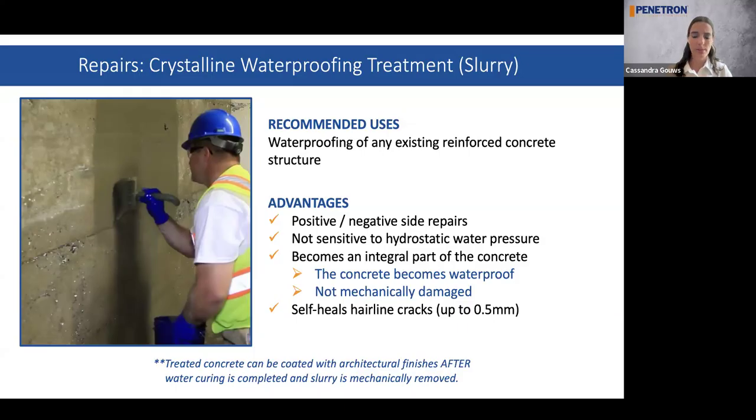And what I mean by that is if you've got, let's say, a basement, right, a concrete basement, your walls are leaking. Traditionally, you'd have to remove the backfill, repair the membrane from the outside, and then put the backfill back again. With the crystalline technology, you don't need to do that. You can leave everything in place and you can now repair it from the inside. The inside is the negative side.